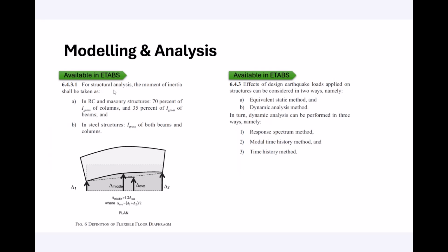Exceptions would be for large openings in the buildings, or lengthy buildings where the stiffness is distributed such that some portion of the building, for example, the image shown here, which is going out of plane in the middle part of the building, then you will get the ratio greater than 1.2, and you will have to use the flexible or the semi-rigid diaphragm.